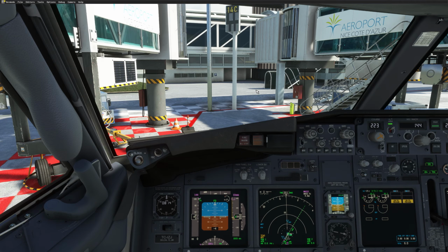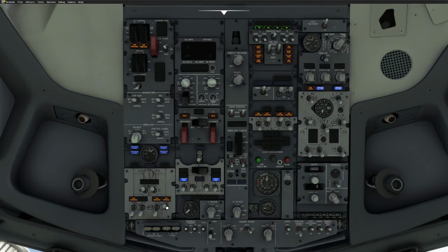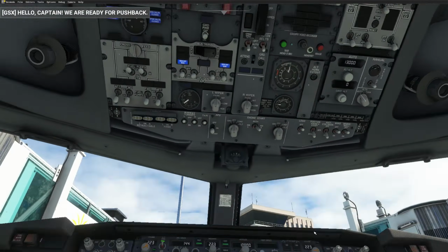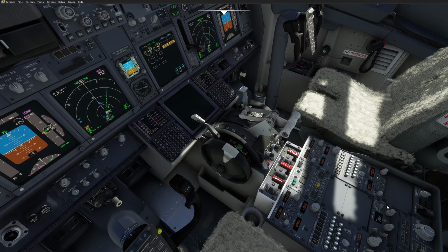So before start flow, pumps, fuel pumps on. Then we go to the right across here to find the seat belts, make sure it's on. Then if we are clear to pressurize, we pressurize the hydraulic. We will check that we have 3000 psi in a minute. And then we go down here and we put anti-collision light on. Now that this is done, just put your transponder to altitude reporting. I put it myself on altitude reporting.